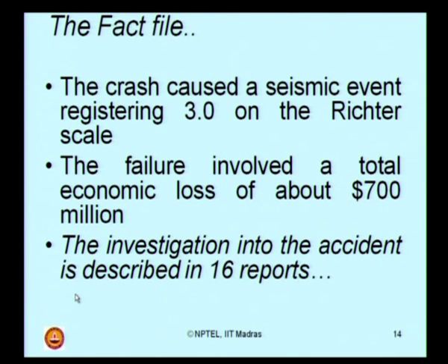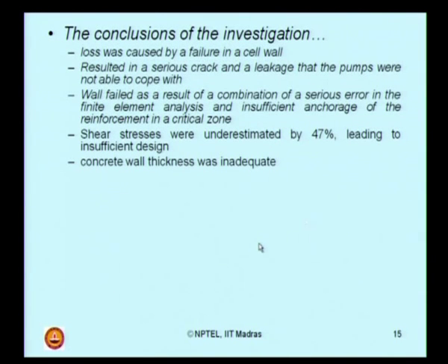The investigation into the accident is described in about 16 reports available in the standard literature in the public domain. I am just giving the brief conclusion of those investigations. The loss was identified to be caused by a failure in a cell wall of the platform. It resulted in a serious crack and a leakage that the pumps were not able to cope with.